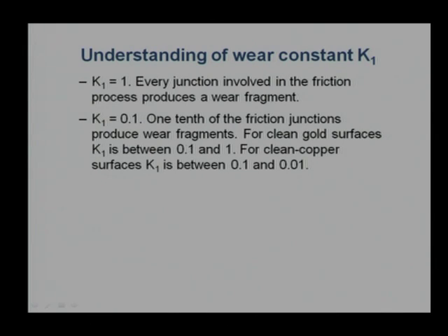There is a possibility of this. So, we say that wear rate is high. However, when you treat clean copper, the wear rate is slightly lower, about 1/10 of gold itself. You say that for clean copper, this K1 will be in a range of 0.1 to 0.01. That means using copper is better than using gold.